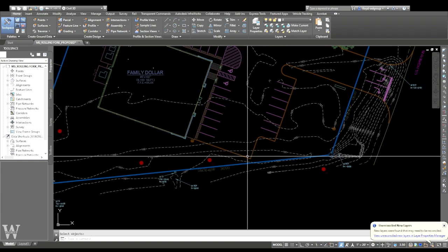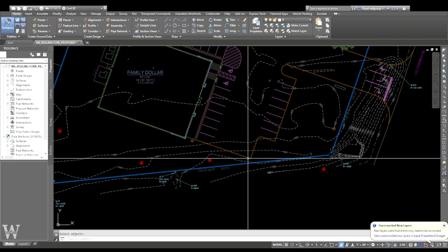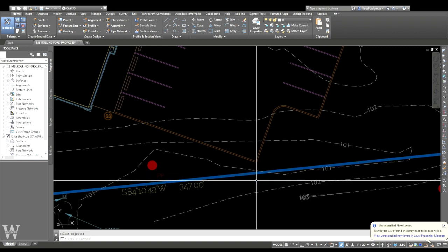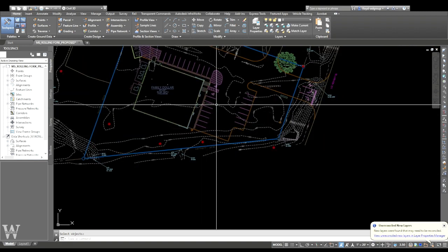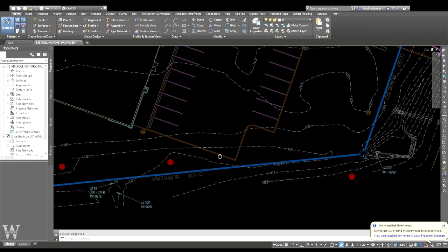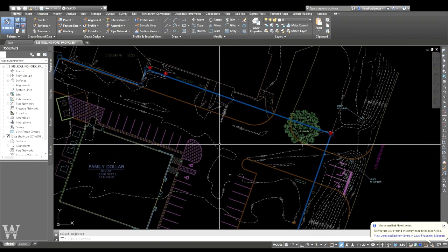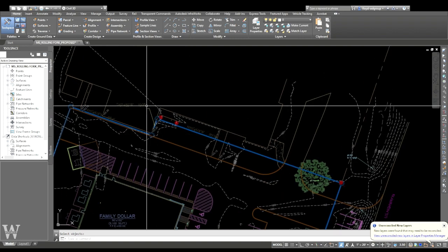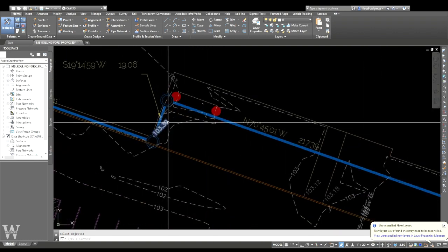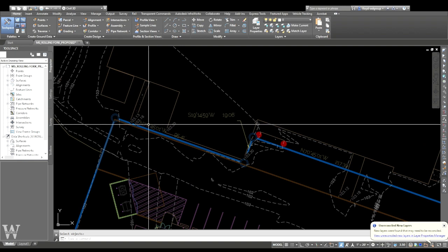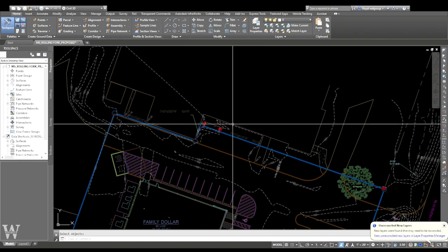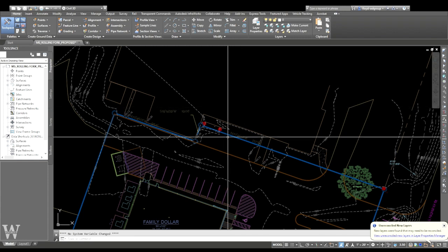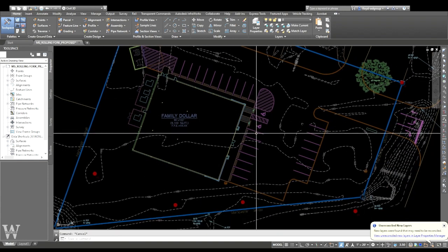So what I know is that it's a little low on this side. It's 2 feet from here to here of slope. So what we know is that this existing building that's next door, an old slab that's here, is like 103.3, 103. It could be 104, 105, 103 and a half is probably what that building was at. Just trying to determine what elevation we want to set it out.